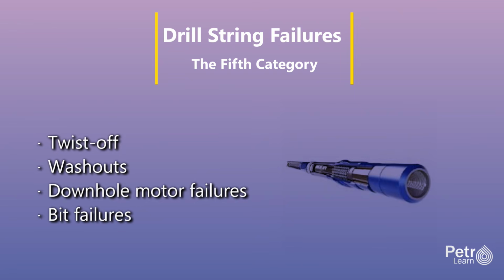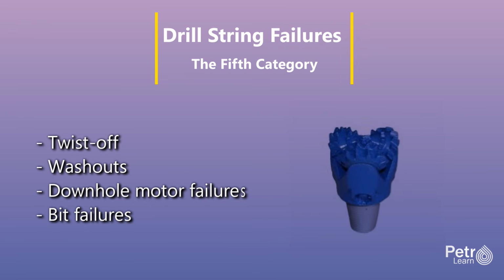Downhole motor failures stop rotation at the bit, while the surface equipment appears to be functioning normally, indicated by loss of penetration rate and changes in pressure and torque readings. Bit failures in drilling operations typically arise from wear, damage, or improper operating parameters, and they affect both roller cone and PDC bits in distinct but predictable ways. For roller cone bits, common failures include bearing wear, cone cracking, lost cones, and broken or worn teeth caused by excessive weight on bit, high vibration, or abrasive formations.